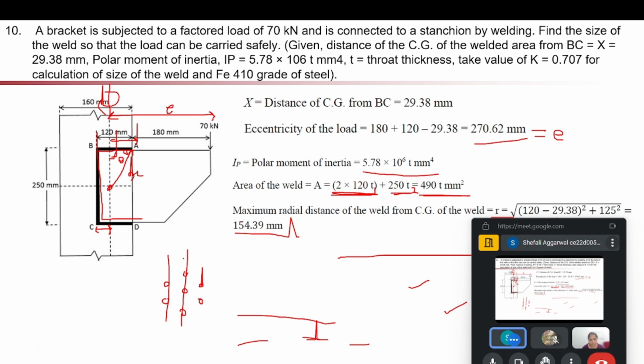Because we had an assumption that the bolts have an equal distribution of load, we will not be considering the bolt values of the first 2 bolts. If the failure occurs, it cannot be that only 2 bolts are failing, right?